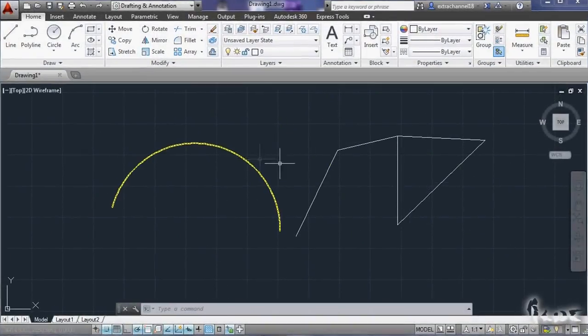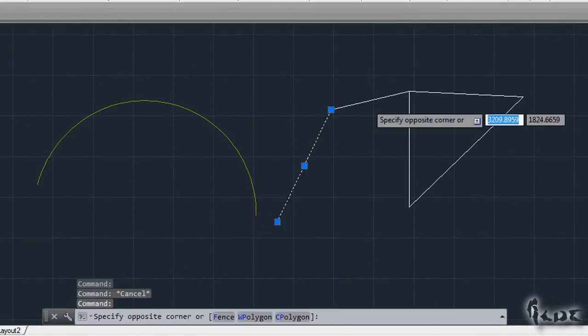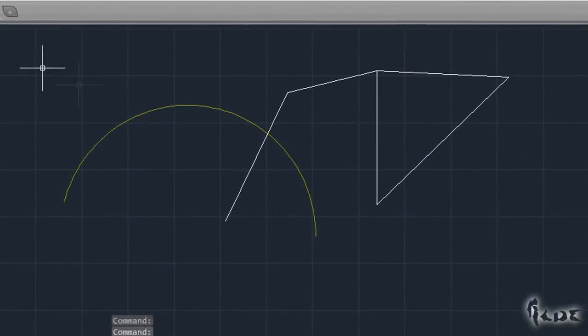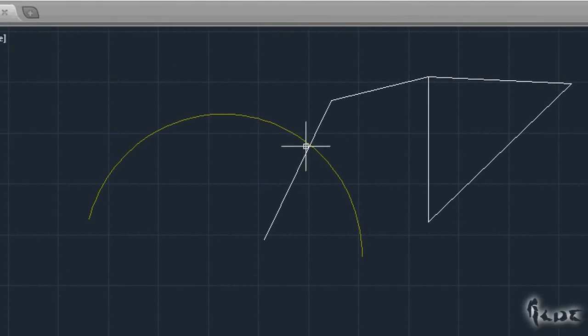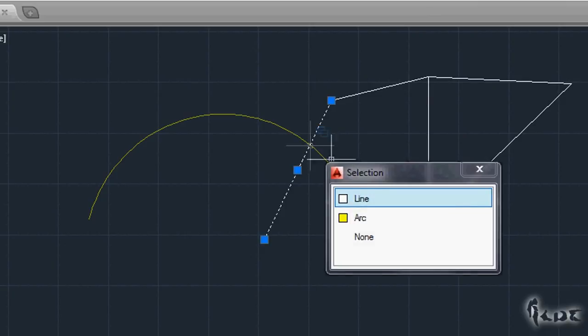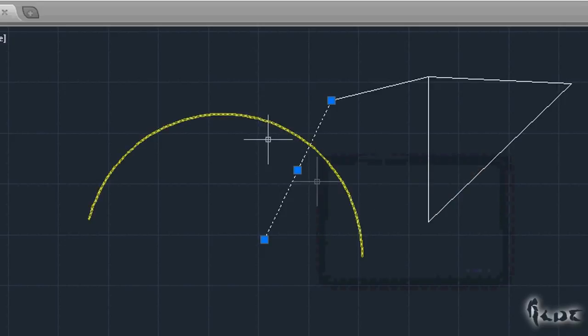The objects selected all together will be moved or edited or modified in the same exact way. Undo the selection by pressing Escape from your keyboard. In case there is overlapping between two or more objects in one point, two small blue rectangles will appear next to your pointer. If you click, you can choose which object to select.